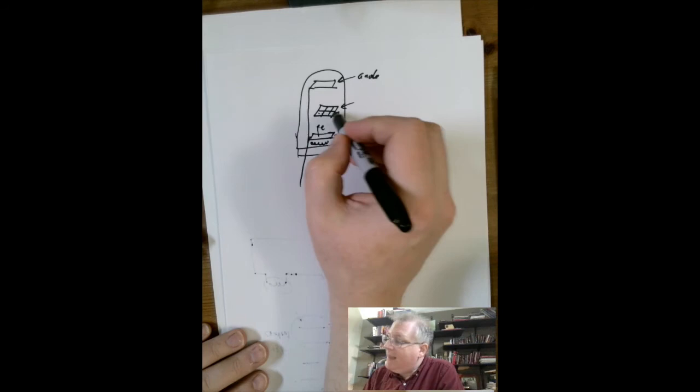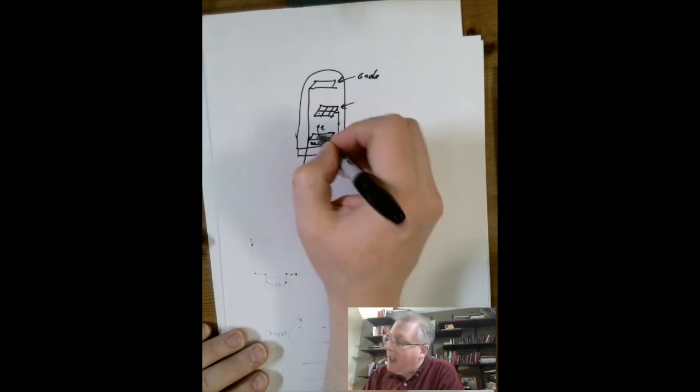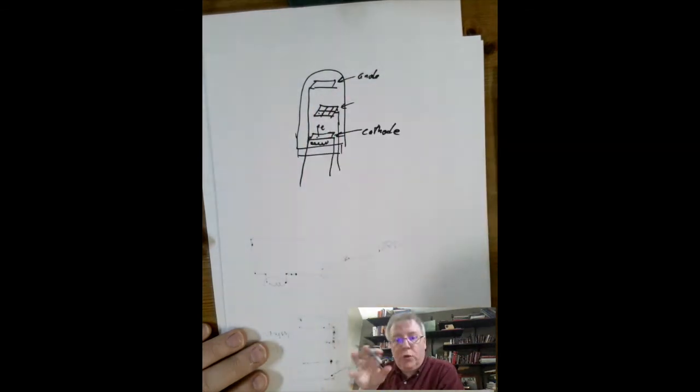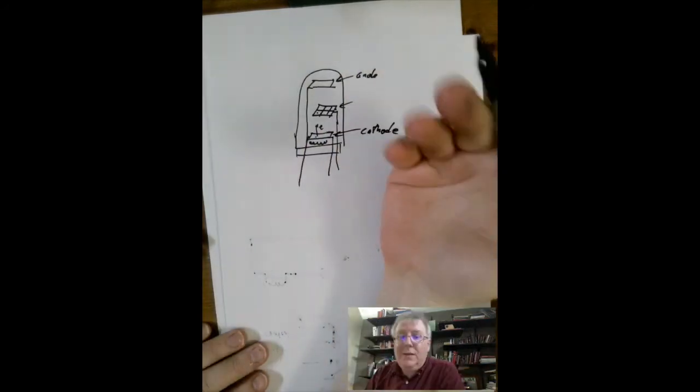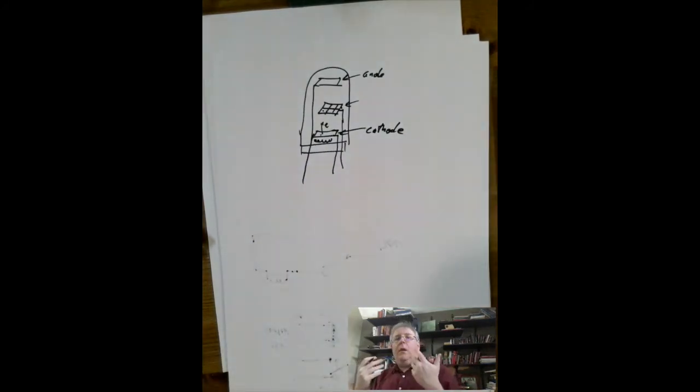So if you put a small voltage on this grid, you can stop the current going from the cathode to the anode. And if you change that voltage, you can dial it around so that you can let lots of electrons through or a few electrons through. So this is a vacuum tube, and this is what you would have used in early radios or early televisions.